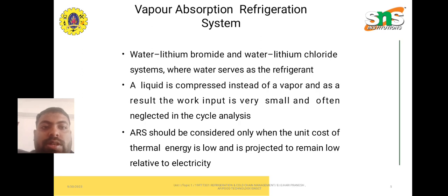Here the systems used are water lithium bromide and water lithium chloride. In this, a liquid is compressed instead of a vapor, and as a result, the work input is very small and often neglected in the cycle analysis. The ARS should be considered only when the unit cost of the thermal energy is low and is projected to remain low relative to electricity.